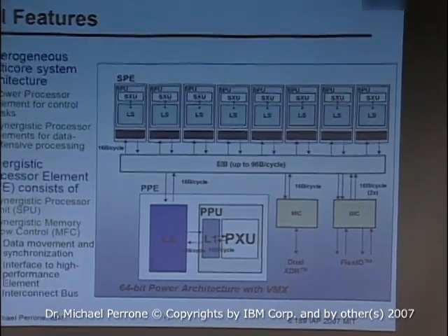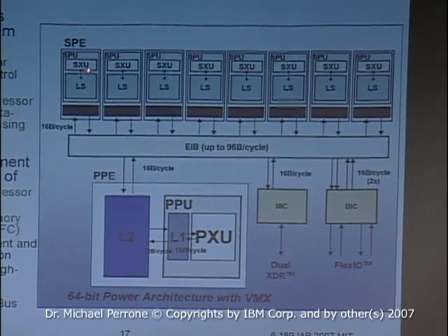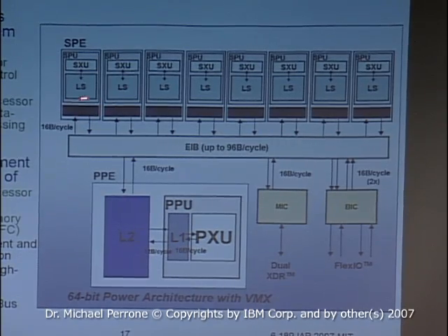It's not very large. It's a quarter of a megabyte, but it's very fast to this SXU, this processing unit. It's only 6 cycles away from that unit. And it's a fully pipelined 6, so that if you feed that pipeline, you can get data every cycle. And here, the thing that you can't read because it's probably too dark is a DMA engine.